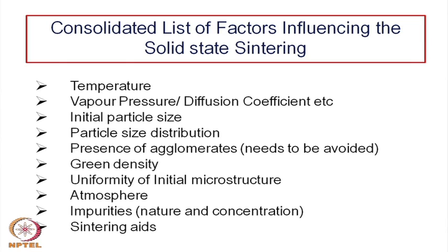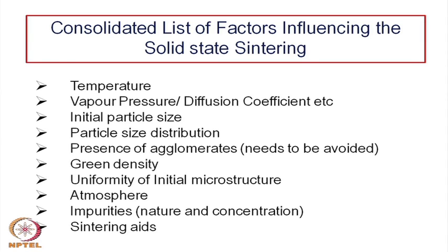So, you need less time, and not only less time, there is also more possibility of getting the theoretical density. Almost all the pores can be eliminated if the particle sizes are finer, and therefore, in ceramics, particularly in advanced ceramics, not the conventional ceramics, particle size or powder preparation is a very important parameter or step in getting the dense materials, right.